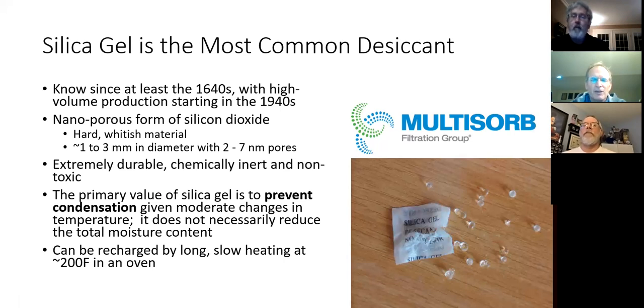It doesn't reduce the humidity a lot, or not in the long run. Once it's freshly recharged, it will certainly reduce humidity, but that's not the real value of it. The real value is that if the temperature drops near the dew point and you're starting to get condensation, particularly in a plastic bag or an enclosure, that condensation immediately gets pulled into the silica gel and has the effect of temporarily reducing the humidity, so you don't get condensation all over the inside of the container. And once the temperature warms up again, it'll release it. So it's not a permanent capture of water. It'll release it or absorb it.